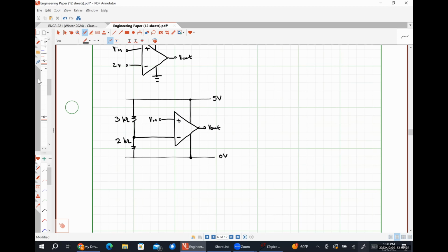So VX will still be defined between those two nodes. So this is the VX that you have, which is going to happen to be negative 30 because we know there's no drop over that 10. If you only put the VX as the drop over the 10 ohm resistor, that's why you were getting 30 volts.